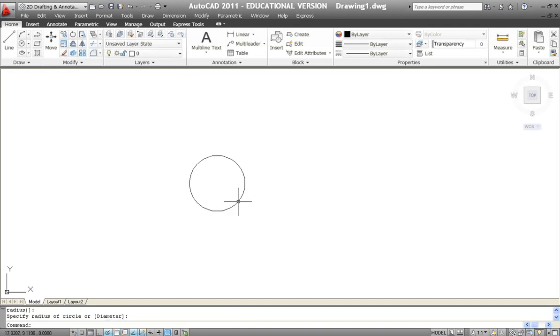So now if you happen to have a circle, and then you need to draw a line, and the line has to go to the center of the circle, you can snap right to the center of the circle. If you want to go with another line to the midpoint of a line, you can grab the midpoint. Just erase those as well. The other button here is the 3D object snap. Unless you're doing a 3D model, you probably want to leave that turned off. It won't make any difference if you're doing two-dimensional work, but it does allow you in 3D modeling to snap to elements on the model itself. For what we're doing in the CAD graphics class, we'll leave it turned off.